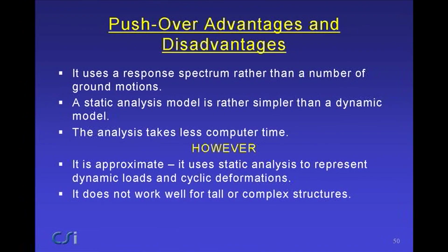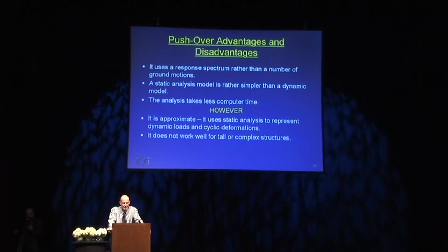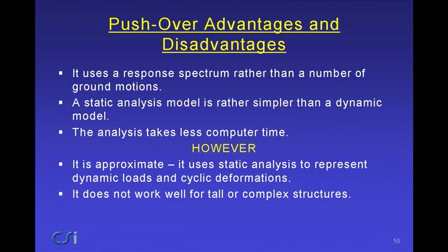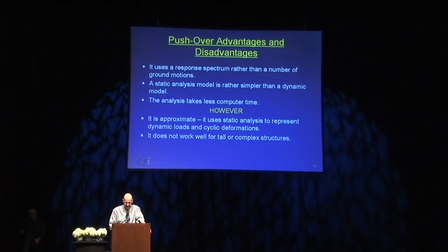Advantages and disadvantages of pushover: you use a response spectrum rather than ground motions. The static analysis model is a little simpler than dynamic, not a lot, but somewhat simpler. And the analysis takes less computer time. However, there are major caveats. Firstly, it is approximate, and the reason is it uses static analysis to represent dynamic loads and cyclic deformations. There's no cyclic deformation in a pushover analysis. And it does not work well for tall structures, and it doesn't work well for complex structures.